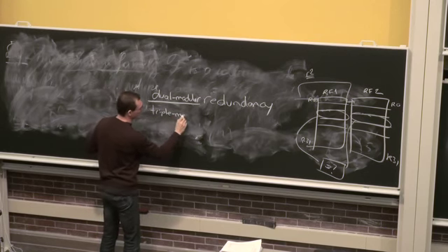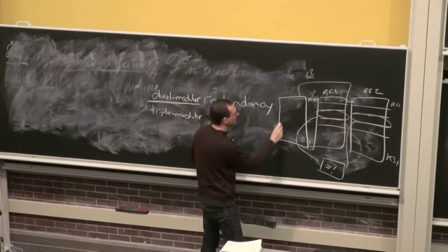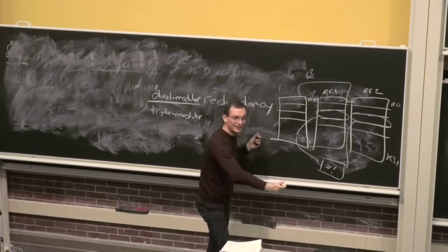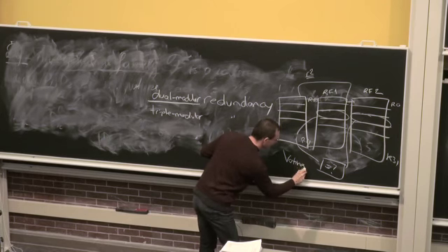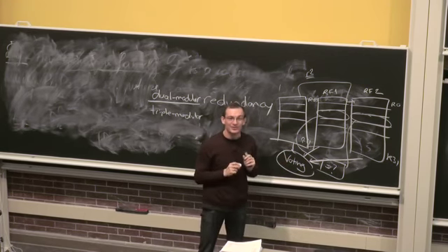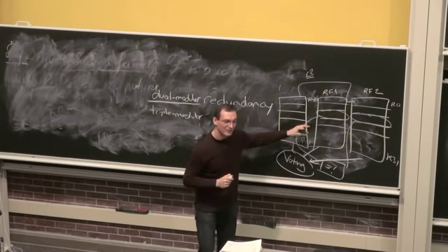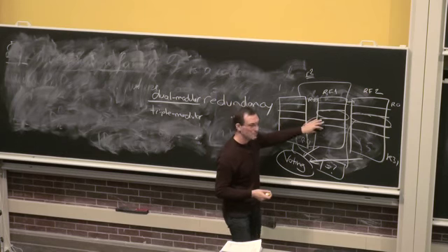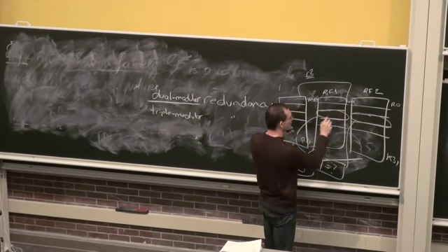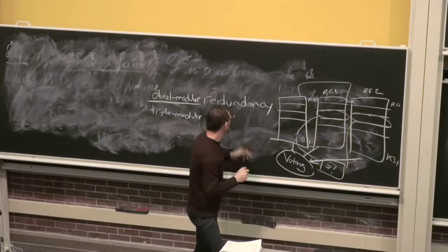next step, if you will, have triple modular redundancy, and have another copy. Right? Now you read 3 copies of R2, and you do a voting. You have a voting circuit that takes the 3 copies and picks the common value and assumes that that's the correct value. Right? So this way you can actually figure out which one is correct. Again, nothing is absolutely correct, but the probability that all values or multiple values will have the same error at the same location is unlikely. Right? Make sense?